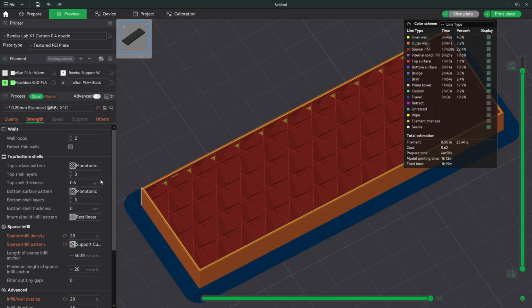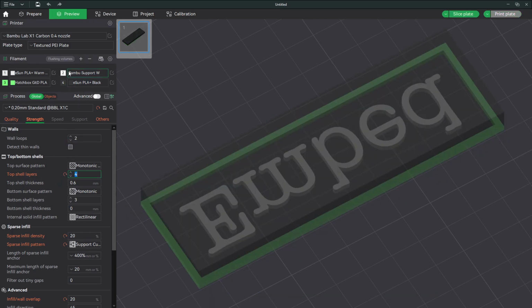Lining the infill up, usually I can do it in 3. Sometimes I do it in 4, at least when we're talking 0.2 millimeter layers. If you're printing smaller layers like 0.12 or 0.08 or something like that, you need more. Turn it up some. You need that volume of material there. In fact, I'd say when I'm printing in 0.12 layers, I usually have like 6 or 7, just to make sure that it actually gives a nice clean surface.